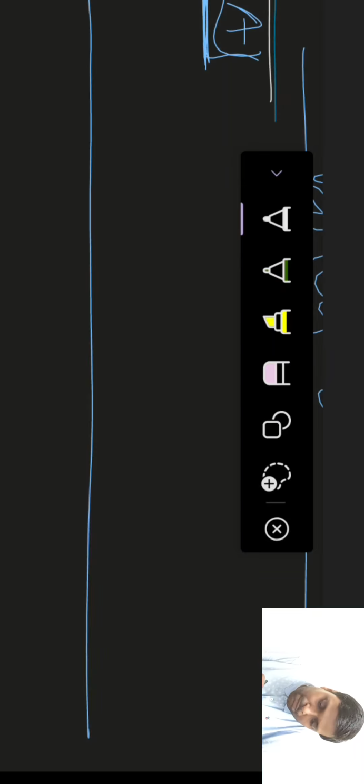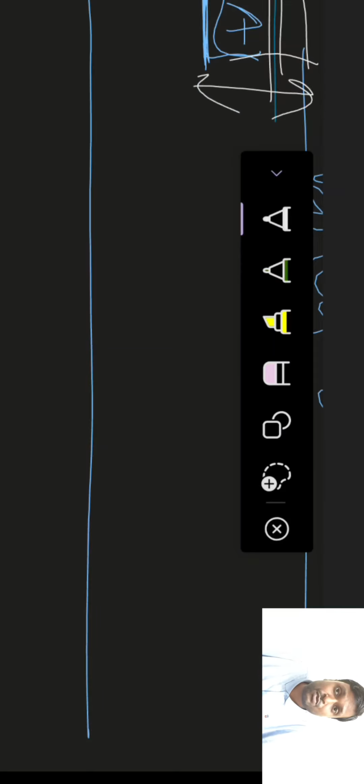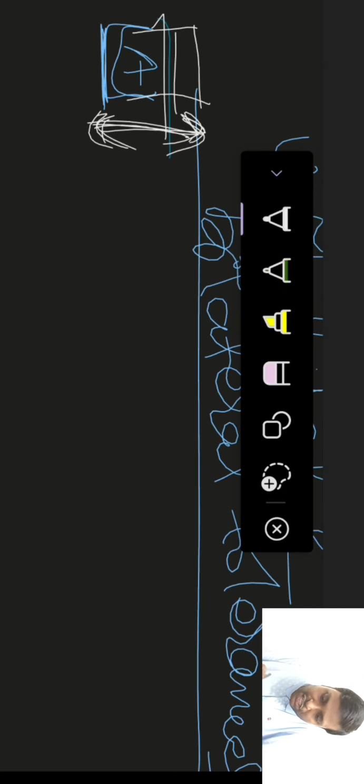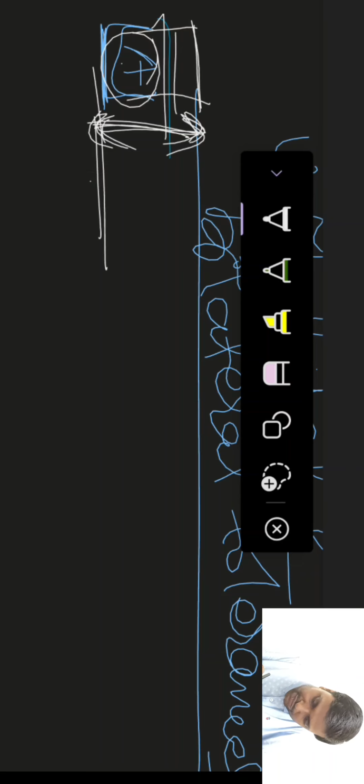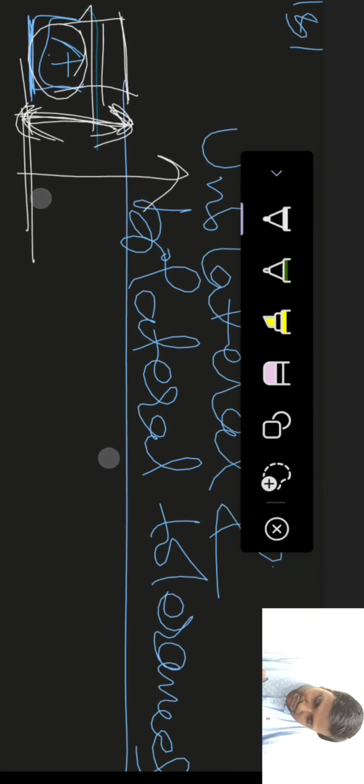So what will be the upper limit? The upper limit will depend on what deviation in the limits is allowed, or you can say what tolerance we are providing. This deviation in size is nothing but the tolerance. If the tolerance is this much, the upper deviation will be this much. Once I write A, the fundamental deviation is fixed. So suppose the tolerance is this much, then this will be the upper deviation. In this case, this will be the tolerance.